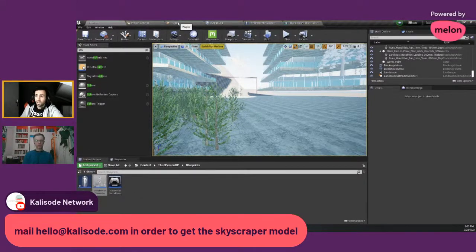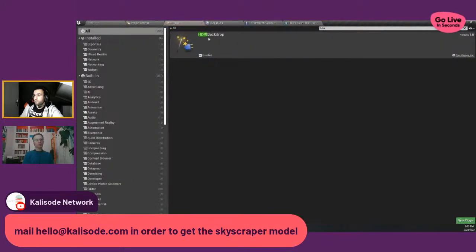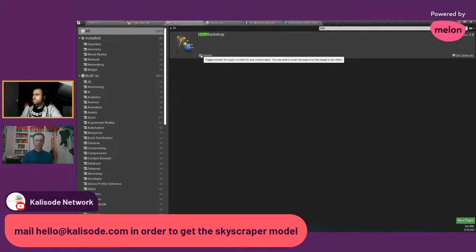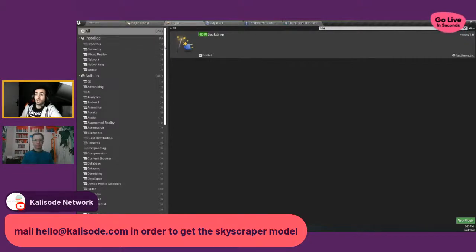What I'm going to recommend is to go to Edit, Plugins, and I've already typed it before. Just type HDRI, and there is this plugin called HDRI Backdrop. Is this coming from the marketplace? It's already in the engine, I guess. Yeah, it's within the engine. Okay, it's an out of the box package.